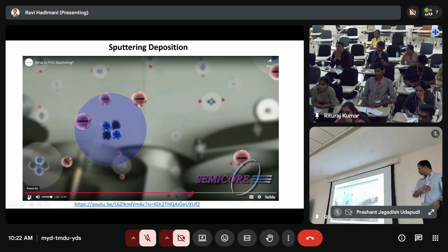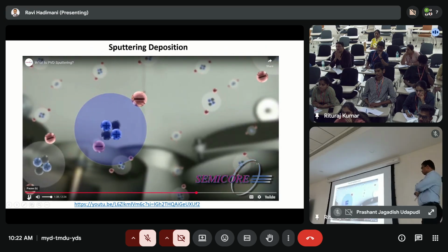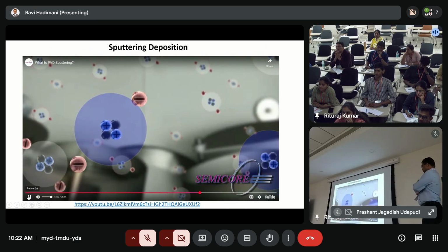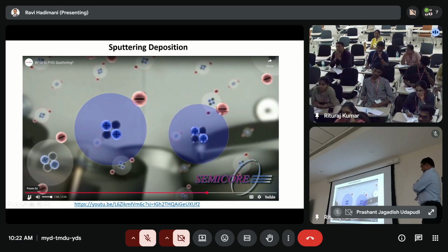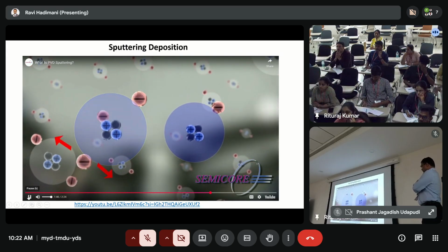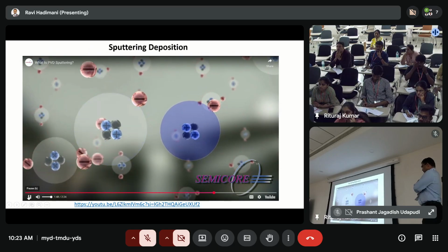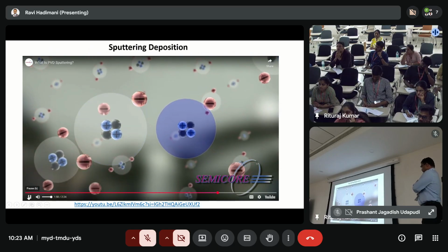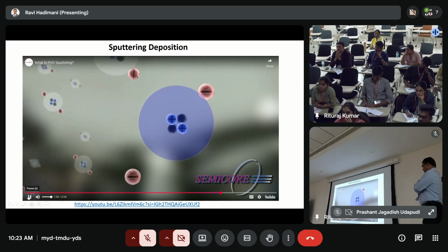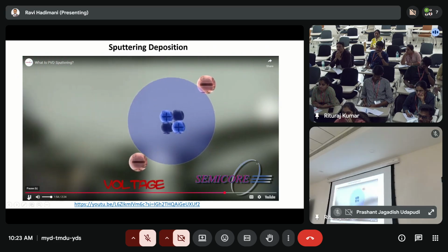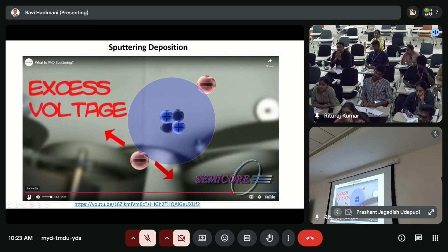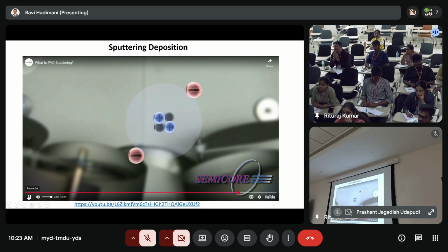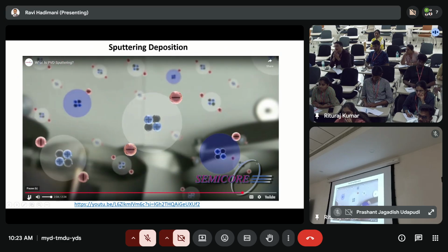The positively charged ions will recombine with free electrons to create a neutral atom again. The light from the plasma is created when the ions recombine with free electrons into a lower energy state. When a free electron recombines with an ion, it has a voltage. The ion needs less voltage, so this excess voltage is let off in a light. The light is the plasma glow that is seen during processing.